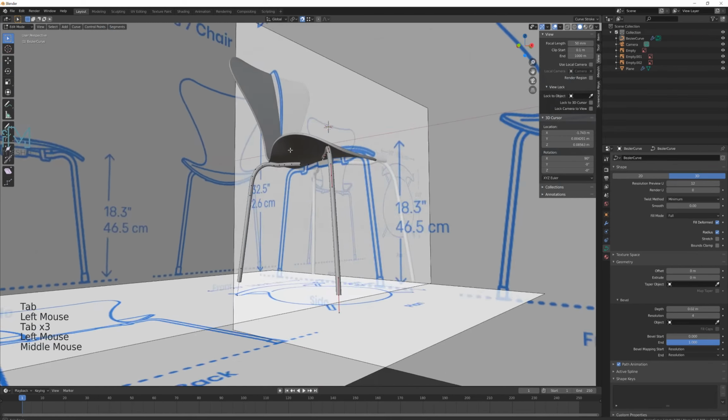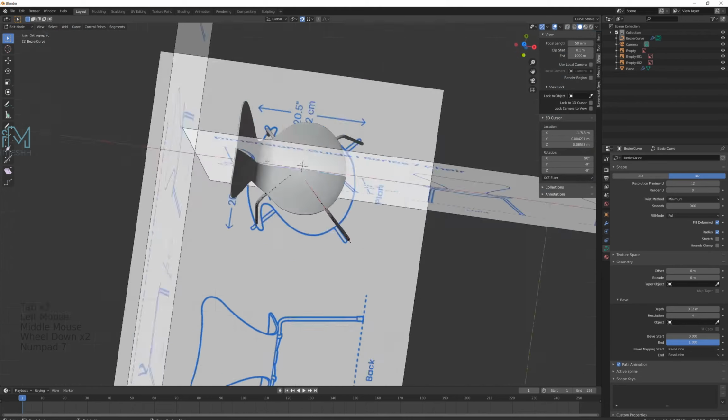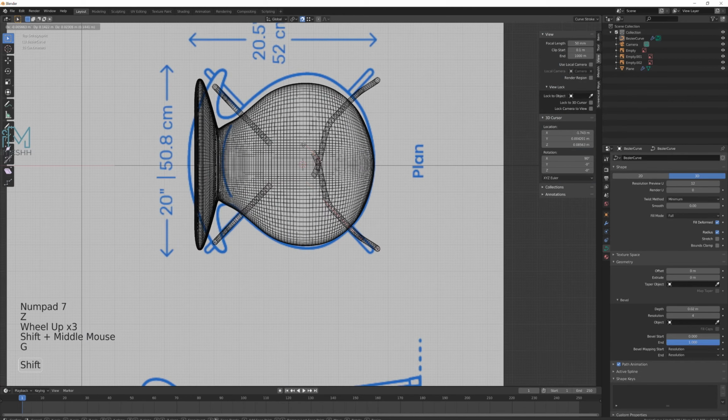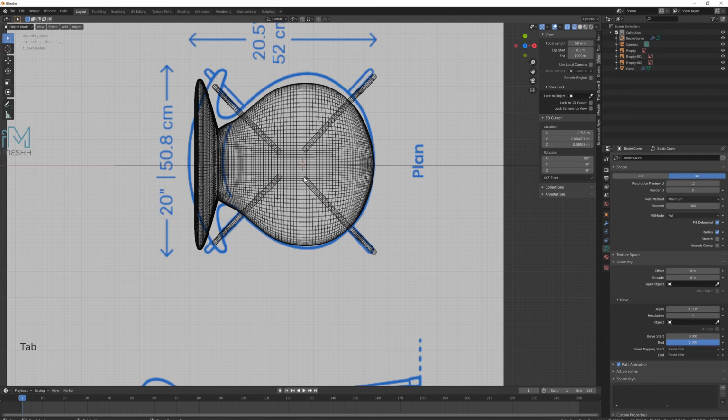These actually look like they go a bit further in. So let's just move these in a bit closer to the middle. Whoops. Turn off this thing here with Shift Tab, and move these in straight. And this line has actually gone off funny, so let's move this back. Okay. I'm going to do Shift S and cursor to selected, and now add a...